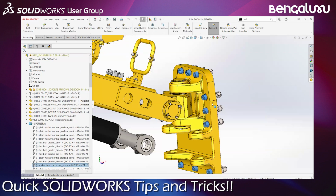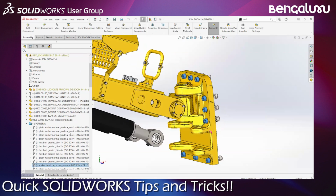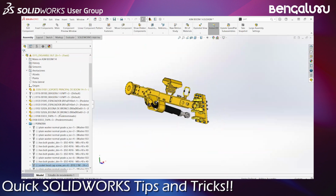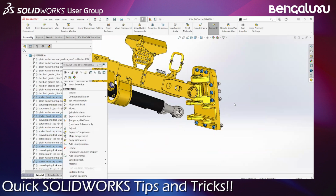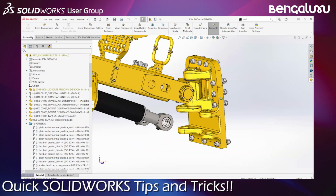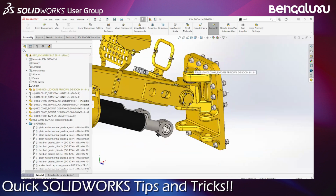So when I hit that, SolidWorks automatically selects all the identical components available in this entire assembly. And it also highlights here in the feature manager tree as well as here. So I can right click and simply say hide to hide all of them at once. And since these are some standard components, when I say standard component, these are nuts, bolts, whatever screws, right? That is coming from SolidWorks toolbox.